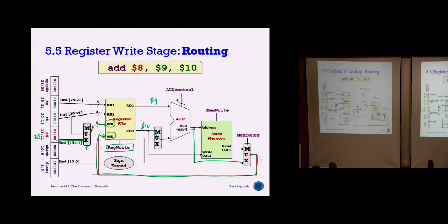So that is the last stage. So this last stage is only there if it is an instruction that is going to update the register. Okay, if there's no need to update the register, then I don't have this stage. Okay, almost all instructions will have this last stage, correct? Because effectively you're doing an operation and you're going to write back to a register. Okay, only an instruction like store word, where you're taking data and writing to memory, then there is no write back stage. Other than that, almost all instructions that you see will have some form of write back.